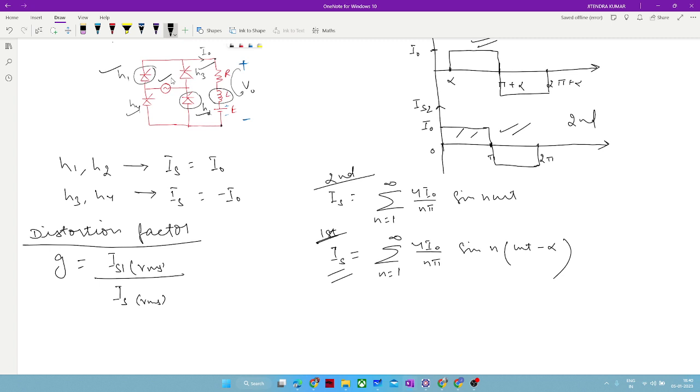If you had some of those, they would get accumulated with those components of your current, and that would lead to active power. But now it won't. So now you want to know what the useful content of this waveform is. For that purpose only, we do these distortion factor calculations and total harmonic distortion, to see how much it is.